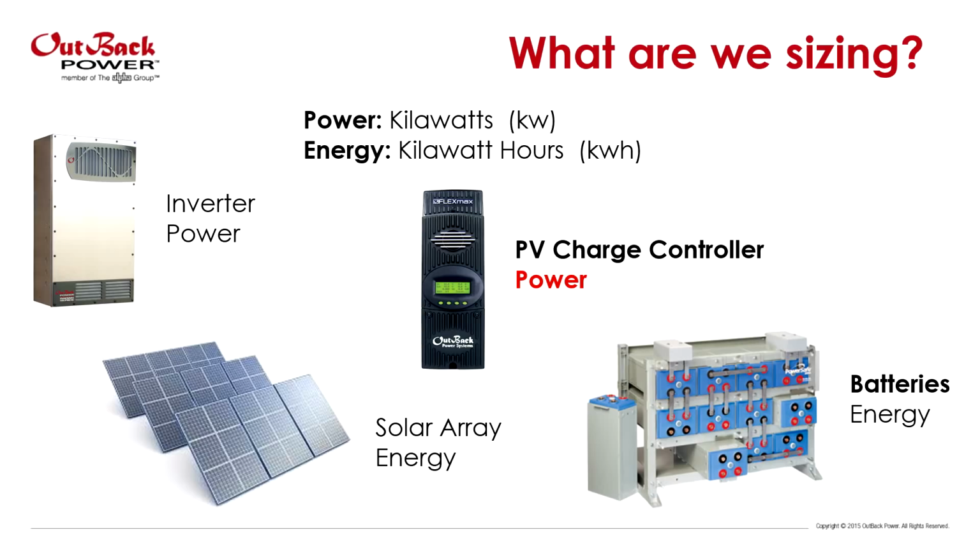And then last is the charge controller. The charge controller is sized based off power, and you'll see the calculations later. But remember, this charge controller is in between the PV array and the battery. You've already sized the PV array and the batteries based on energy, so now you need to make sure that the charge controller can pass through that power from the PV to be able to fully charge the batteries.